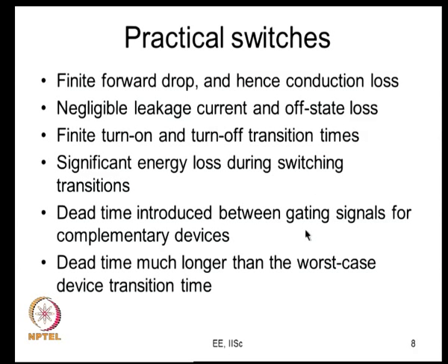The other consequence is that a dead time needs to be introduced between the gating signals for the complementary devices. When the devices turn on and turn off instantaneously, you can switch the complementary devices with gating signals which are exactly complementary to one another. Now, if they take a certain amount of time to turn on and turn off, and one device is on and you want to turn on the second device, can you do the two simultaneously? It is better not to.